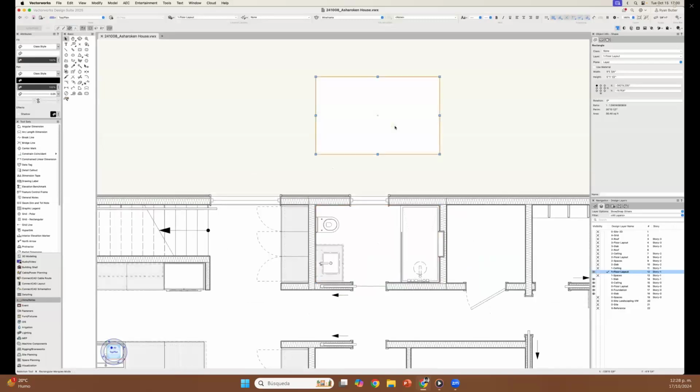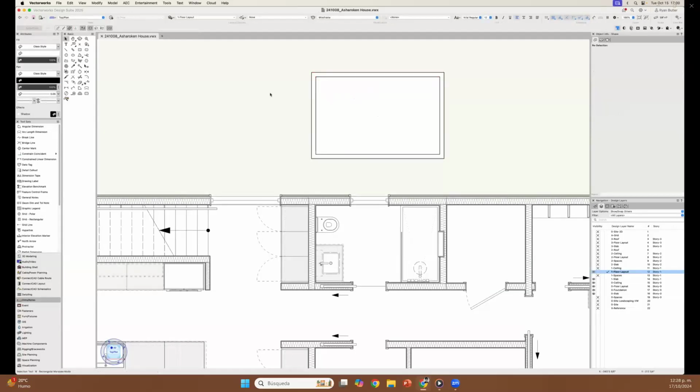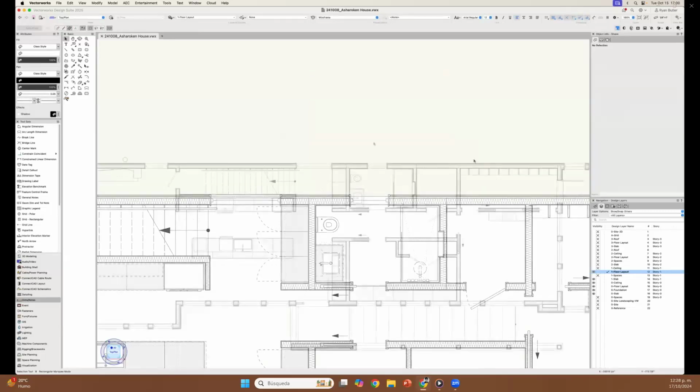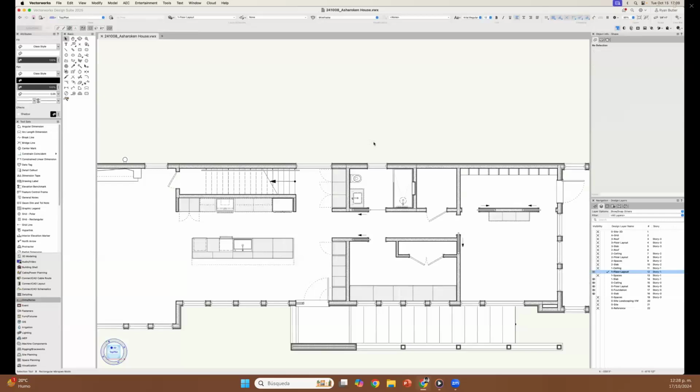Like that. And then you could draw a wall and snap to that geometry as well. So you can trace that if you like that shape. So that's very easy to get precise measurements. Now, when dealing with windows and doors, I tend to group those insertions together because they all go into walls.